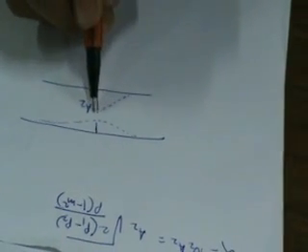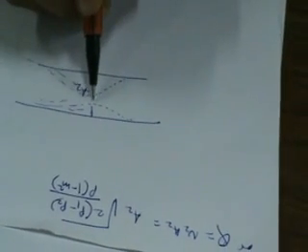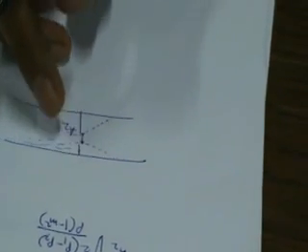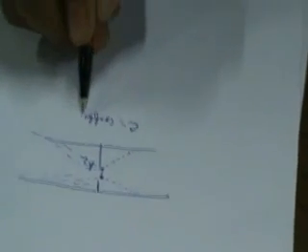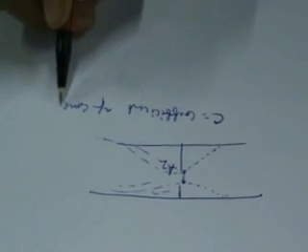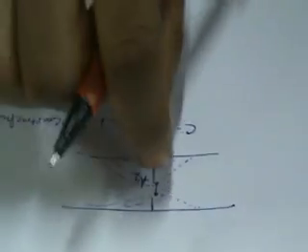The actual area through which the air is flowing will not be A2 but somewhat less than A2, and we bring in a factor which is called C. This is the coefficient of contraction, to calculate the actual area through which flow is going.